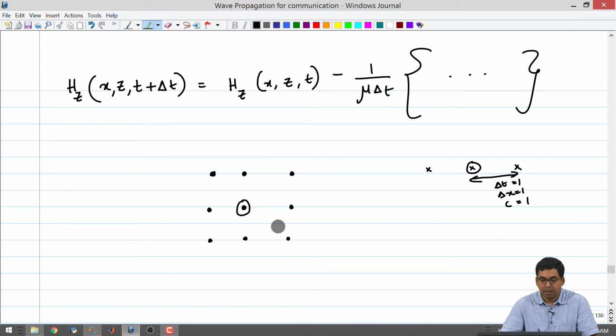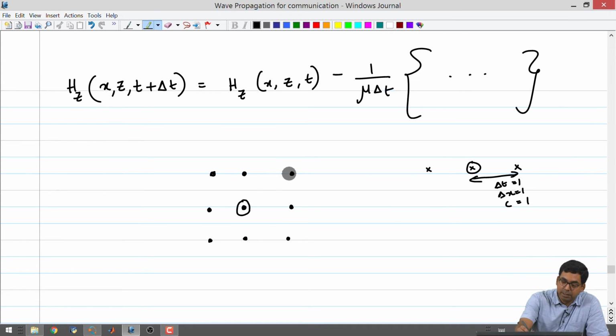Okay. Now, suppose I want this program to remain stable. Okay. The premise is you have to consider this region, all right, because the velocity will be maximum according to the program in this region. Why? Because in one unit time step, you want the wave front to go from here to there to capture this direction propagation. Okay. Otherwise, you will not capture it. In one time step, the wave front has to go in this direction. It travels a longer distance.